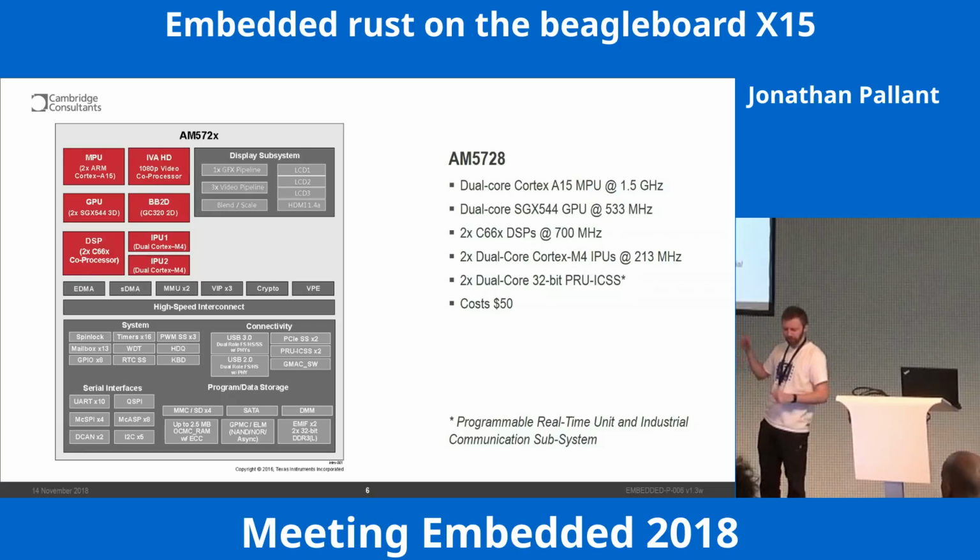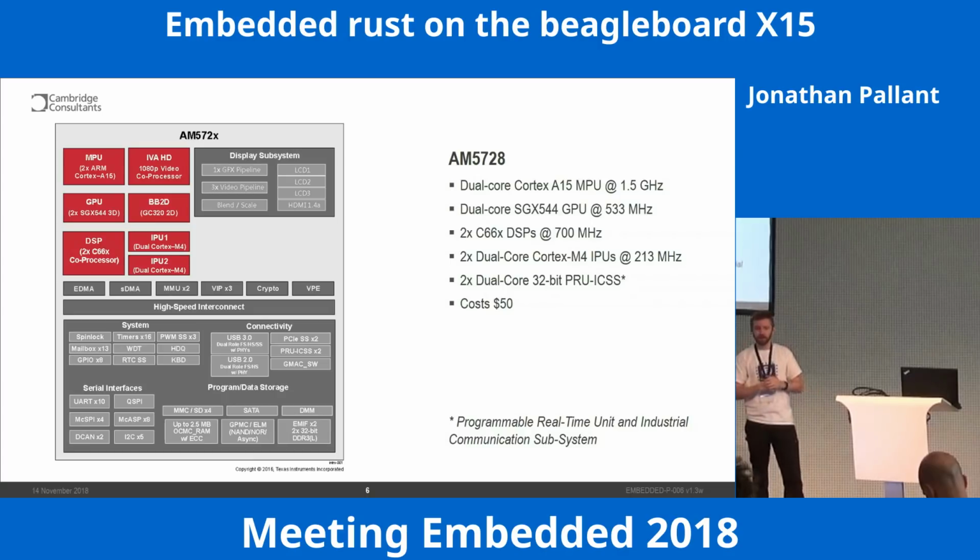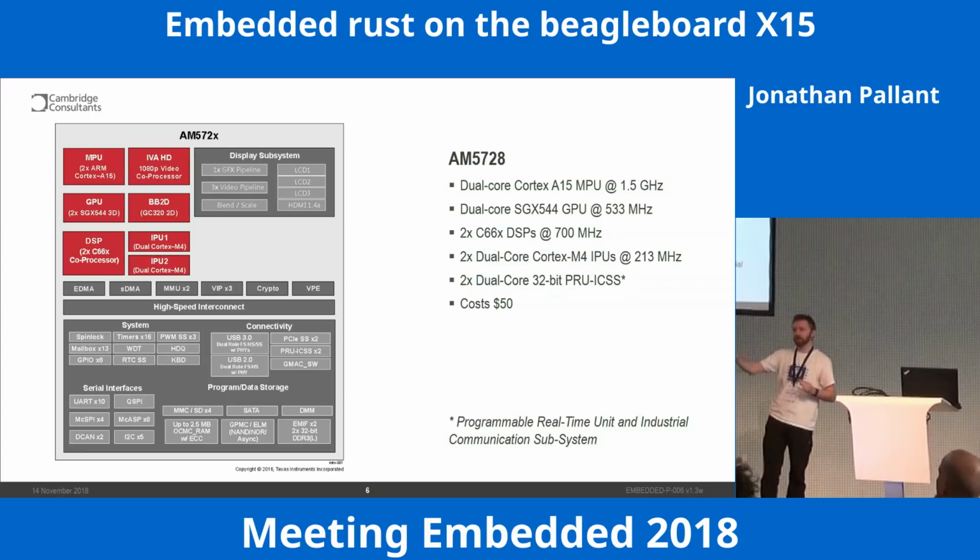We've got a 2D graphics processor in there, but the interesting thing is there are some Cortex M4s. So now we can see, well, we've got some Cortex A's. These are good for running Linux, good for networking, and I've got some Cortex M4s available. Well, I can do my hard real-time over here. It's really hard to do hard real-time on Linux because stuff gets in the way. Whereas if I've got a whole dedicated processor to run whatever it is, look for the incoming interrupt, look for the signal on the wire, analyze some packet, I could do that on its own little dedicated core, and then they share memory with the rest of the CPUs.